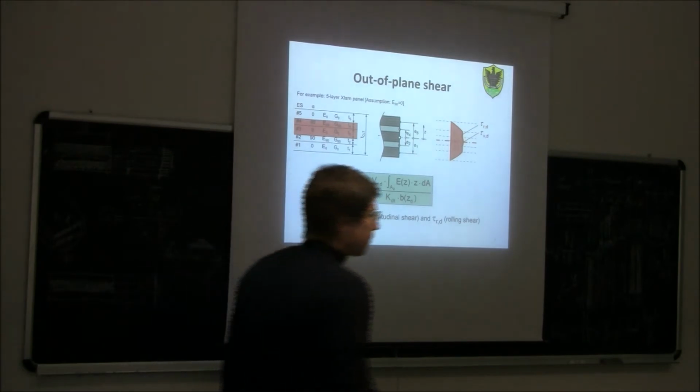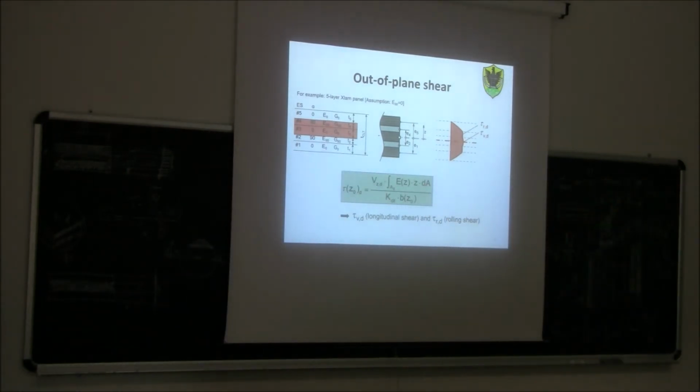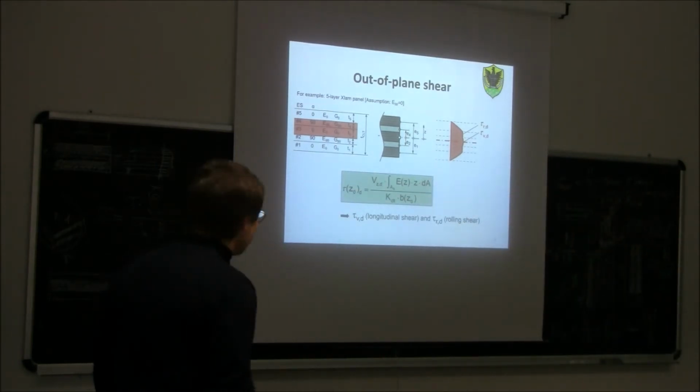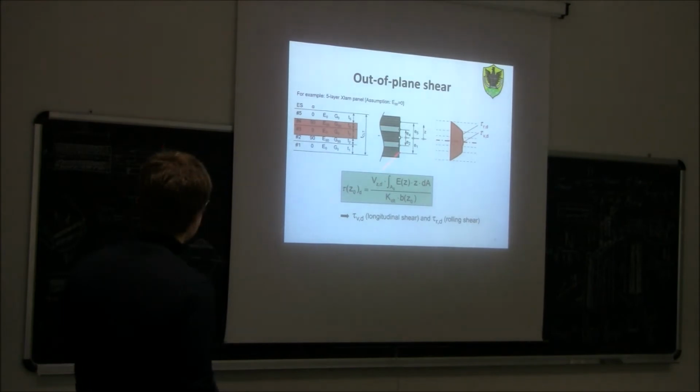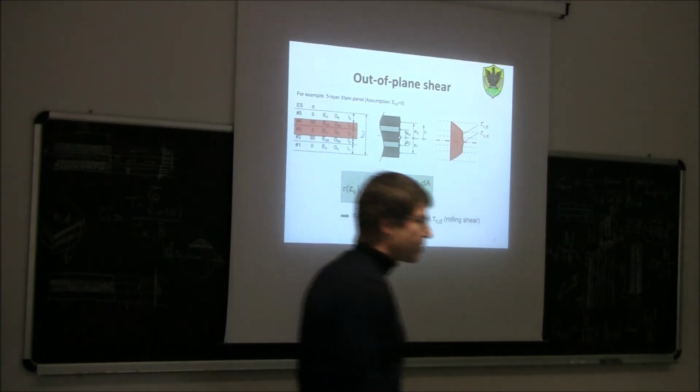Okay, now, if I have to ask you, where would you check the shear strength? So where would you do the ultimate limit state verification of shear? Which fiber? In these three different places here. If you look at the strength demand, where do we have the maximum demand of shear stresses? Here, here, and here. So, which fiber?